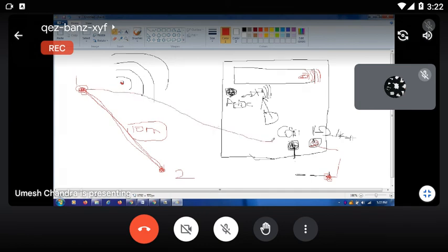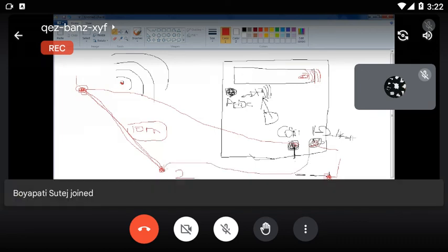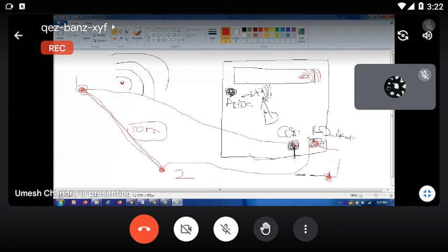The first side you connect to the common point, and the second side to the voltage point. Then you vary the rotary switch and select the symbol which looks like a Wi-Fi. Then press the AC/DC button. If the sound is coming, your wire is good, not broken. If sound is not coming, maybe the middle portion of the wire is broken.